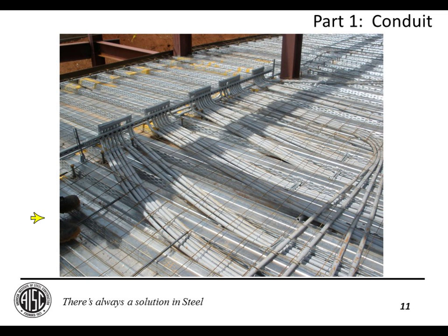So if you look, you can actually see that there are indeed shear studs poking up between this mass of conduit. And unless that conduit has some redeeming structural value of which I am unaware, that beam is most definitely no longer composite. That slab itself is also in a good bit of trouble. All right, so this is obviously one of the extremes, and here we had to do a lot to fix it. We had to spread out the conduit, add in some additional filler beams, reinforce the slab, put a cover plate on that girder that was supposed to be composite. So a great deal of fixing involved.